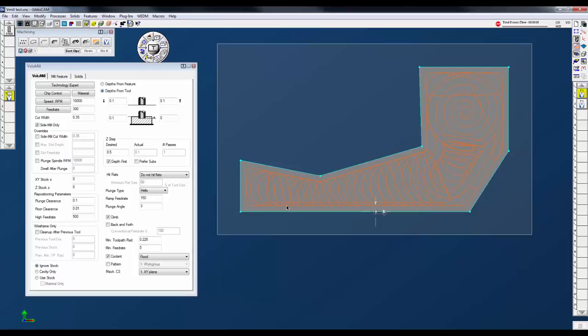It'll come around on an angle and then it'll actually wrap it across and then come around on that curve and then come across. When we're roughing, we may want to just go back and forth. So right here now we have this what's called back and forth. So let's go ahead and just redo it.